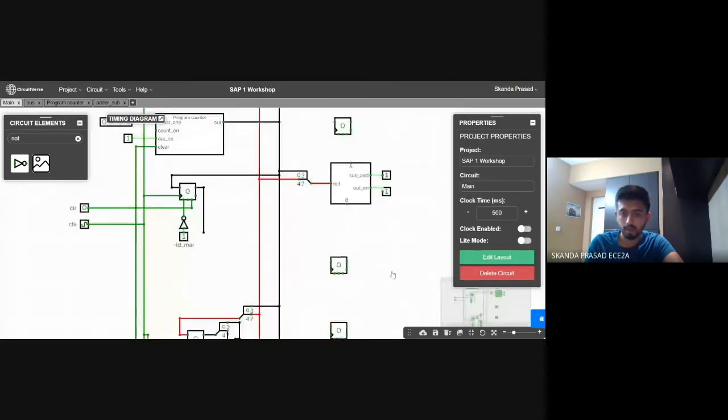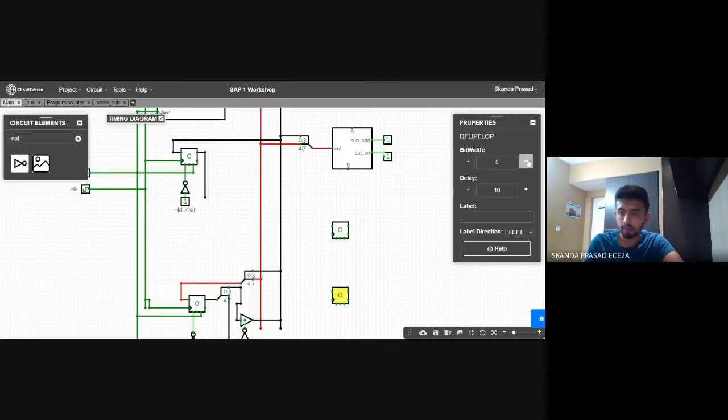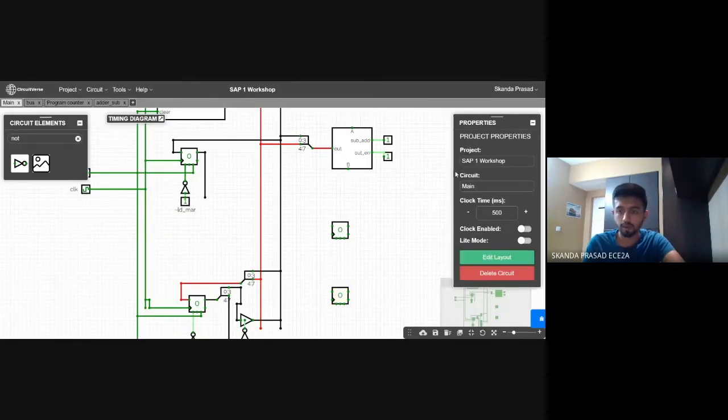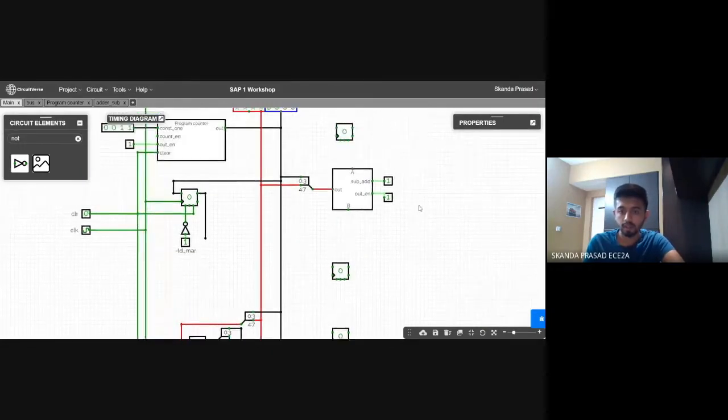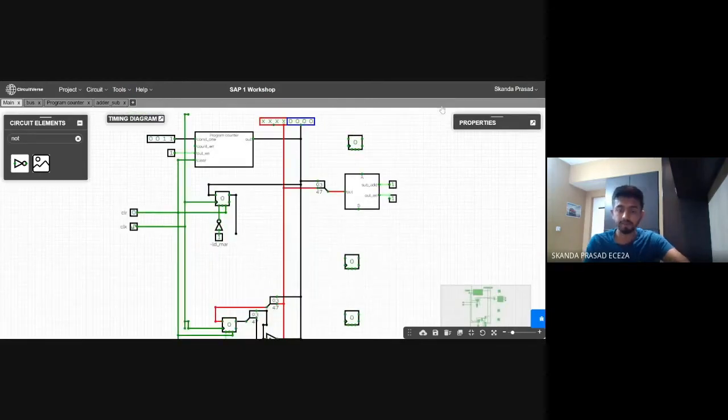Let's move a bit quickly. I'm sorry to do this, but we have to. So we have three registers. Now let's go to the accumulator. What does the accumulator do? It takes input, an 8-bit number, from the bus, stores it, and then gives it to the adder-subtractor. After addition, it will take it back and put it onto the bus. The bus from it will go down, and then the output register will take the final answer.